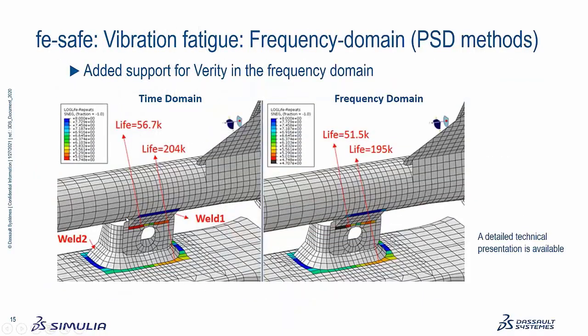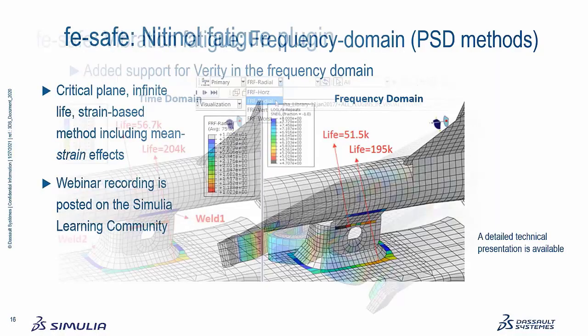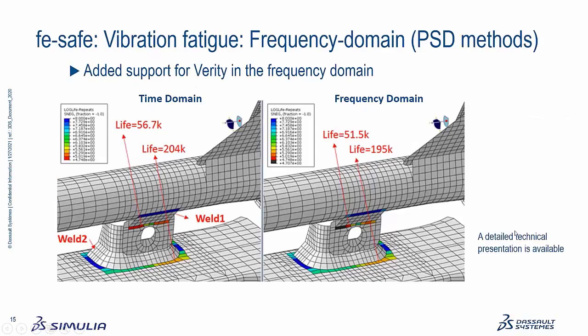Okay. So this one's under vibration fatigue, but really it's a crossover with Verity again, because we now allow you to run Verity in the frequency domain, not just in the time domain modal dynamics style approach. We can now also use the PSD-based methods in the frequency domain. You can see we get good comparable answers between time domain and frequency domain for the welds. Sorry, there is a special presentation on this in quite a bit more detail in the Simulia learning community.